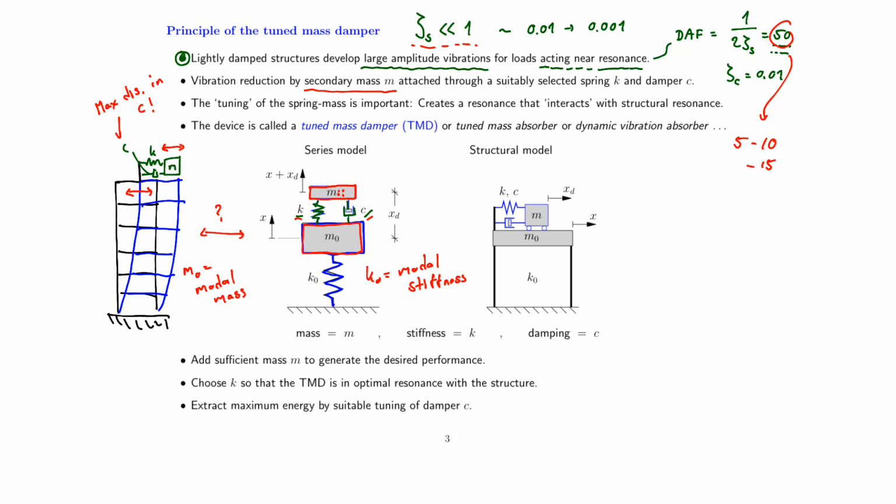And remember that this calibration depends on the normalization of your vibration mode. So, like we did earlier in the course, we normalize the maximum vibration amplitude, or the vibration amplitude at the position of the TMD, to unity, and thereby M0 and K0 become the equivalent structural parameters.